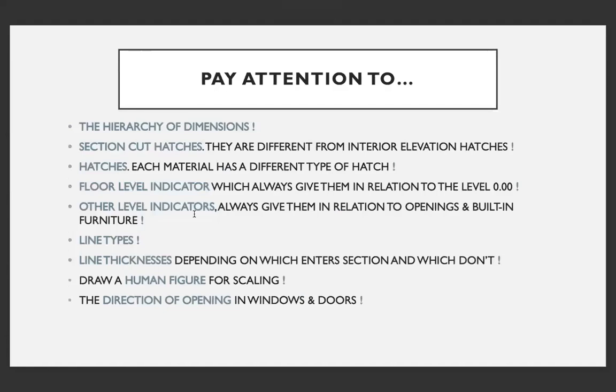You have to pay attention to the hierarchy of the dimensions. Section cut hatches are different from interior elevation hatches. Each material has a different type of hatch. For level indicators, always give them in relationship to the level 0.00, which is ground level.